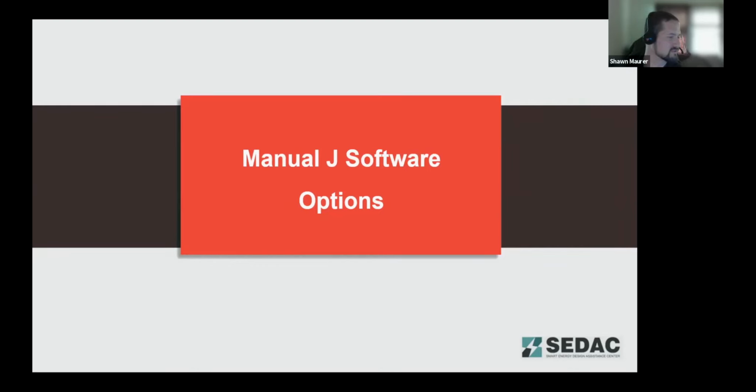Question number 2, rules of thumb for HVAC sizing: grossly oversized equipment almost all the time are a safe bet. You don't want comfort complaints on a cold day. Can lead to problems based on wasted energy due to short cycling of equipment and inadequate dehumidification, or both A and C.